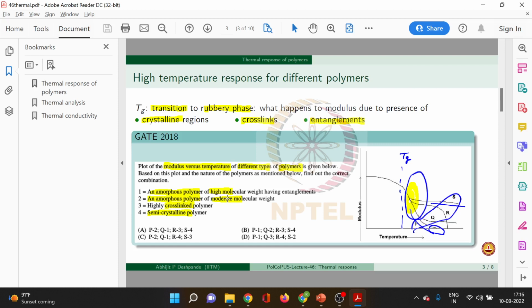So we can say cross-linking is always better in a polymer than crystalline polymers, if you compare modulus? This is all generic cases. For individual cases, you really have to look into it. We can make it a thumb rule: in a cross-linked polymer, it becomes difficult to melt. That is why, in case of thermoset polymers, it goes to a degradation state instead of melting, right?